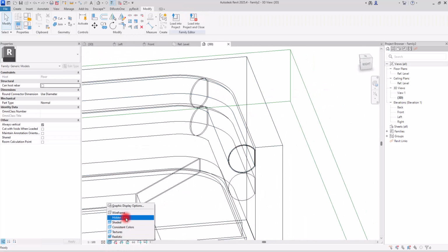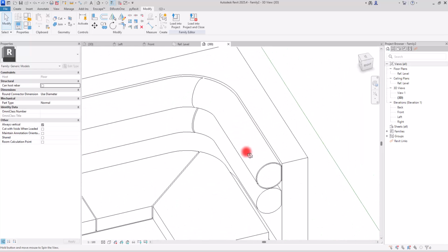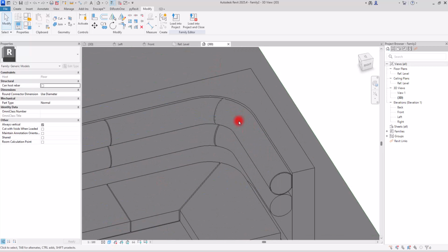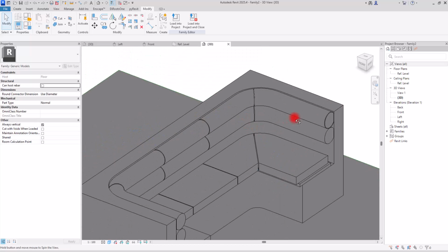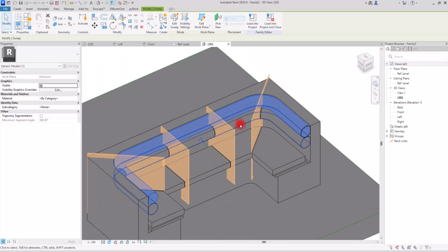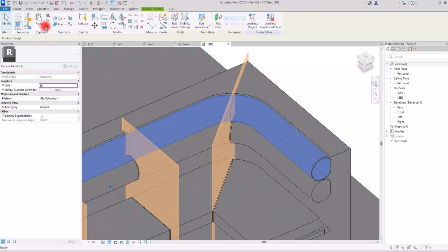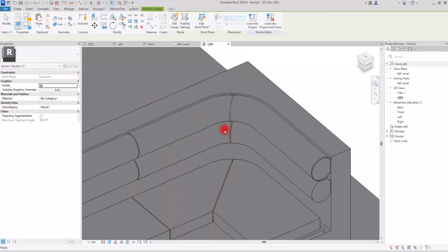Going to put this back on hidden line. Okay, apparently we cannot do this. Okay, we're going to try another way. What we are going to do is to create these sweeps 5 times between these sections: from this part to here, from here to this section in the center, and 2 times in this section. Okay, so I'm going to duplicate it on the same place.